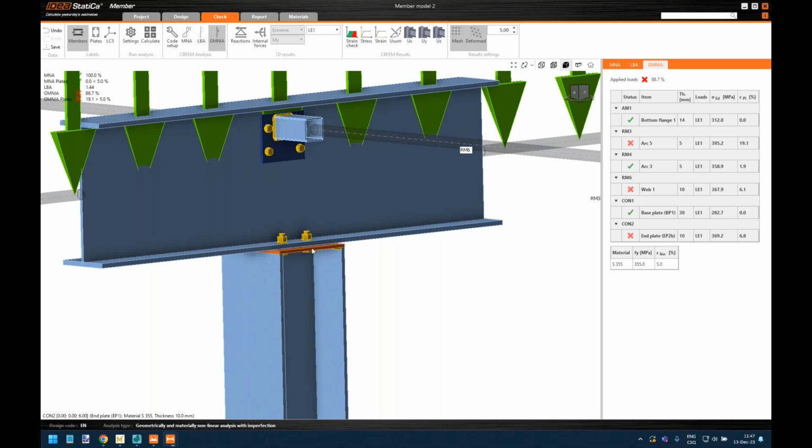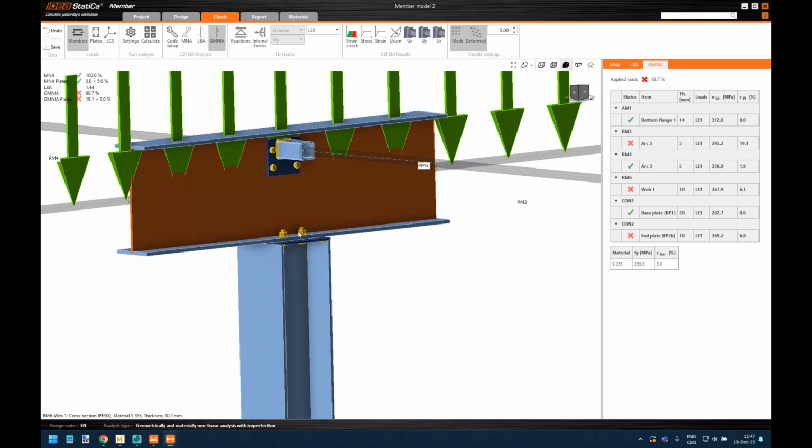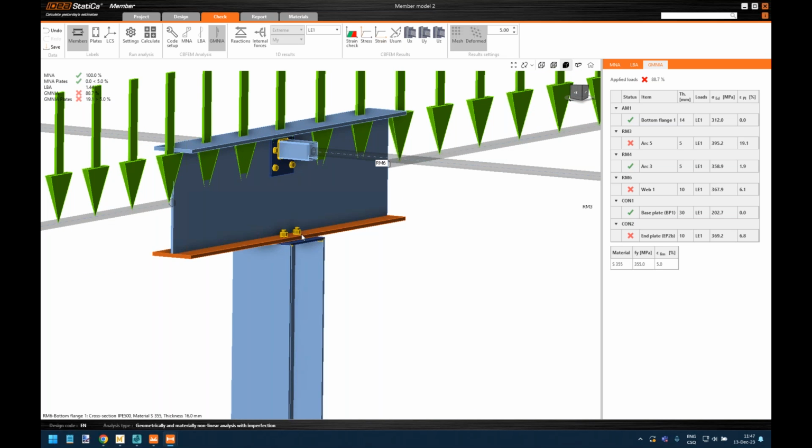But the lower part, with combination of this high web, with combination of this rather weak connection, it basically creates another intermediate hinge around here, in where the beam and the column can deform, rotate, and kind of a bend. So this is what happens.